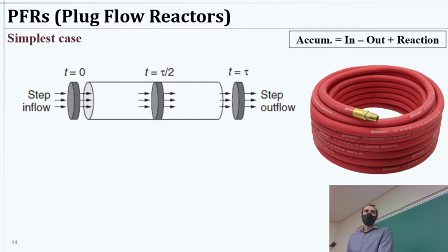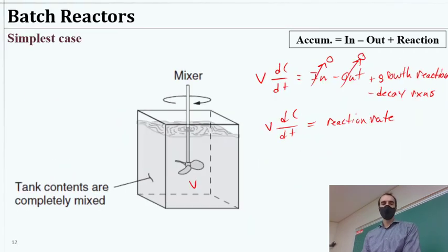For the plug flow reactor, it's both simple, and if you wanted to look at it in a different manner, it's a bit complicated. The simple way is to treat each of these plugs, like I mentioned earlier, like one individual batch reactor. But it's a batch reactor that's going to travel through the pipe, through the reactor. So in the previous case, for the batch reactor, we have it on a basis of time, and we'll end up finding that really what we're looking at is some reaction